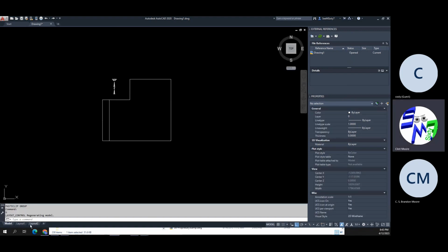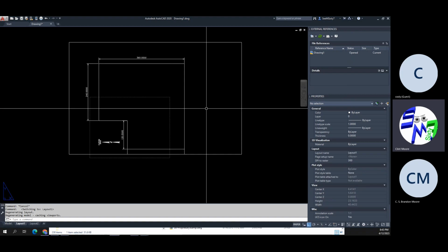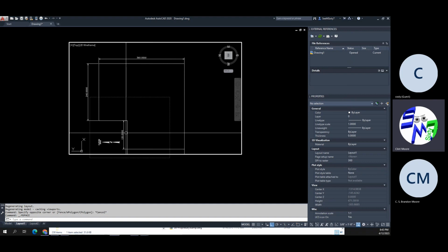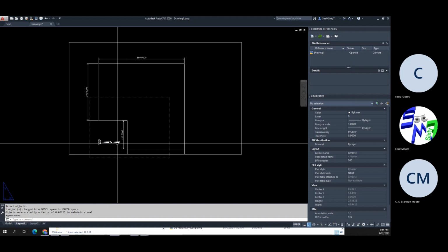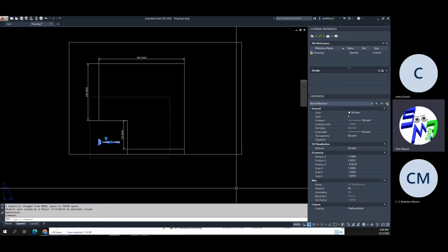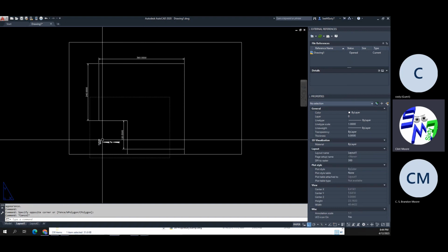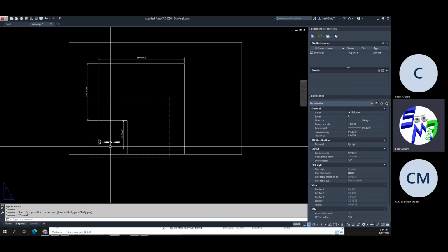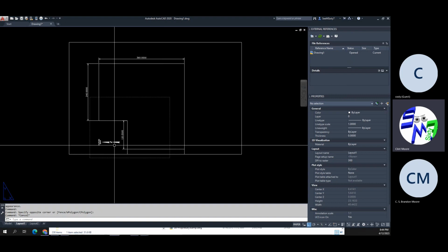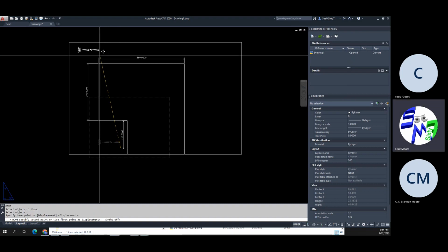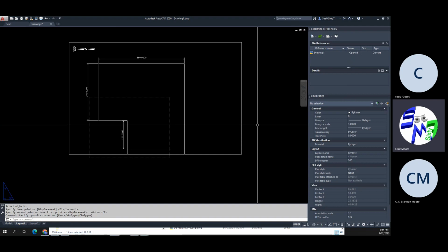Okay, so here I am. So what I can do here is I can go back to layout. I can double click inside here and I can type in change space. I can pick it. And what that does is that moves it. It takes care of the scale factor for me. If you notice, it's now 1. Didn't move it anywhere inside Paperspace, but it just brought it through exactly where it was on the viewport, and it updated the scale of it to make sure it's there. So now I can just grab it and move it because it's actually in Paperspace now. I can move it to the upper left, and there you go.